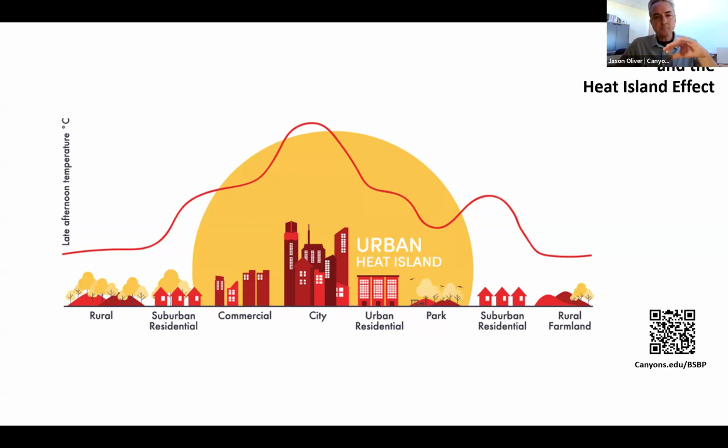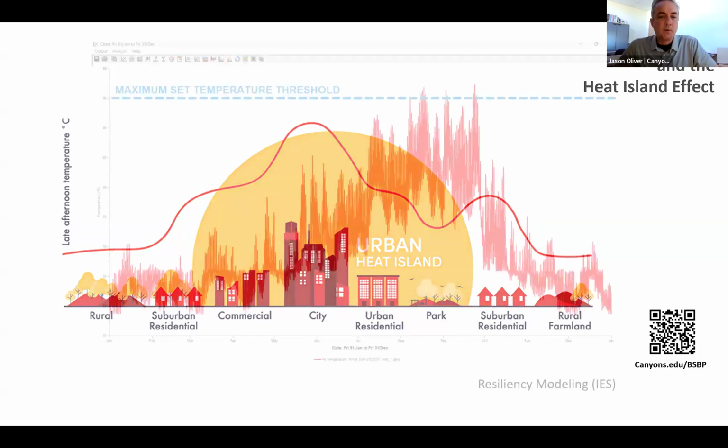regulations that say, when a project, and recently they passed an ordinance requiring apartment buildings in Los Angeles that are built from this point forward, that if the power were to go out for a 2-day period, the interior conditions inside that space cannot get above 82 degrees Fahrenheit. Well, that's great to have that kind of regulation, but how does the building team actually confirm in the design process that that's possible?